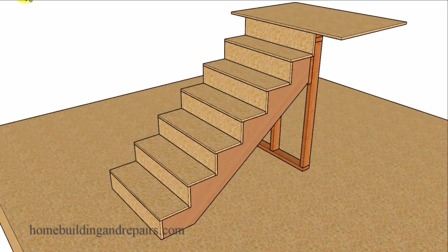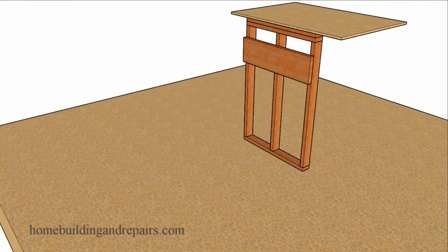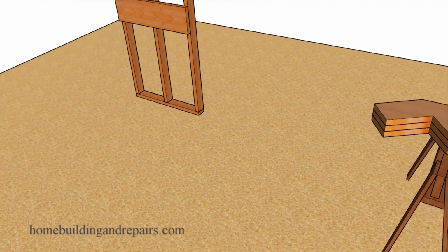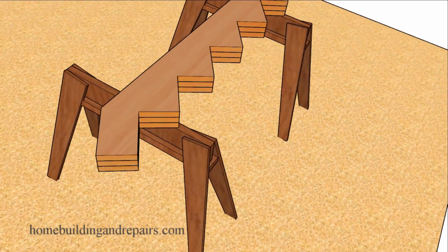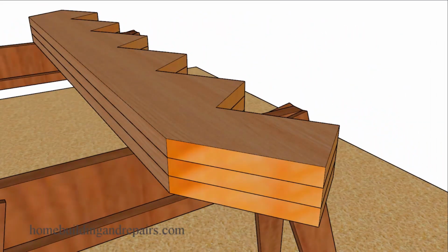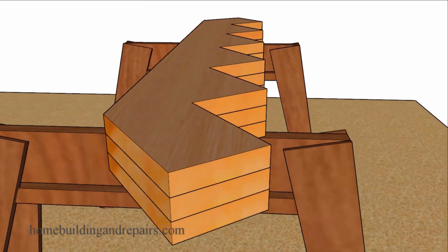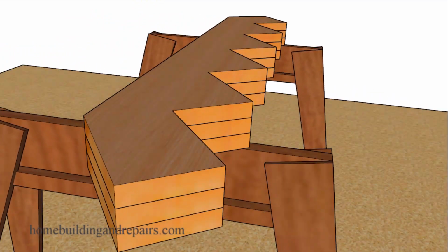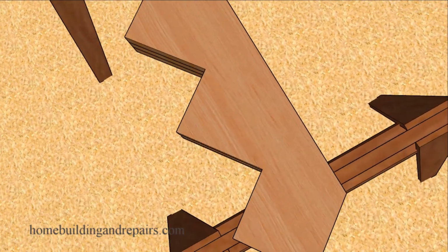Here is another thing you can do when you are building stairs, and you would actually like them to turn out as nice as they possibly can. And that would be to stack your stair stringers on top of each other before they're installed so that you can check for any imperfections. And to do that, you're either going to line the back of it up or line the front of it up, because if your imperfections are only about 1/16 of an inch, then I wouldn't even worry about it. What you're going to be looking for will be imperfections that are going to be a little bit larger.